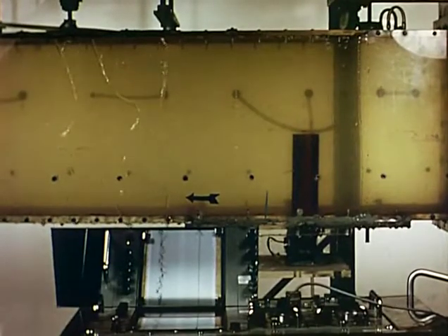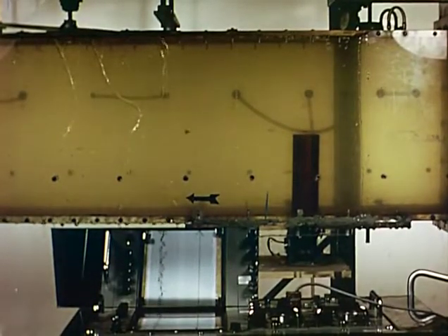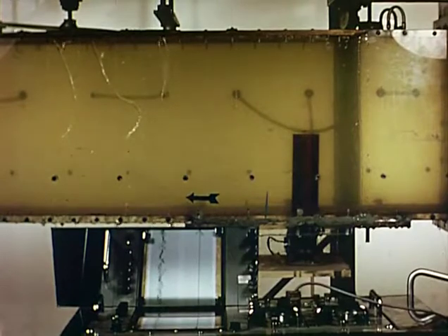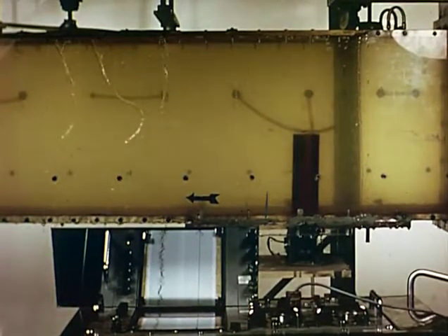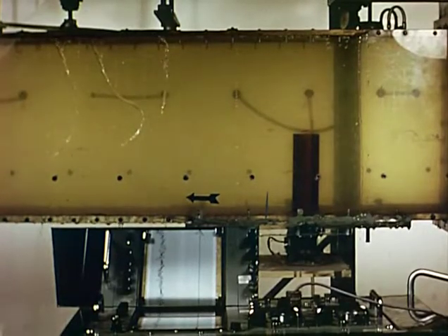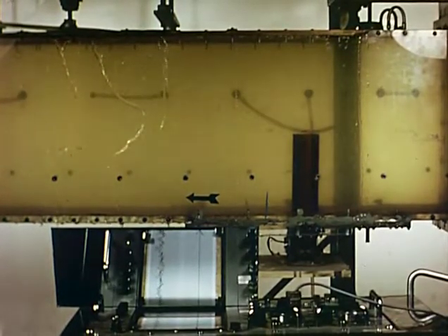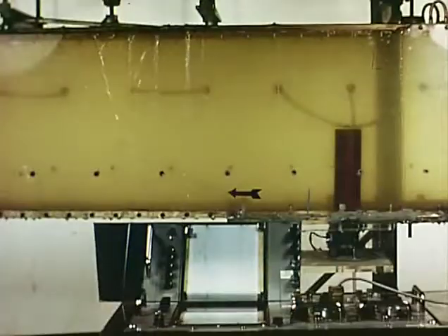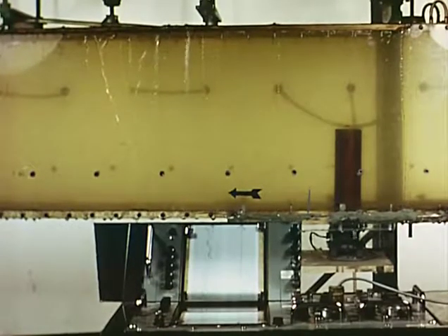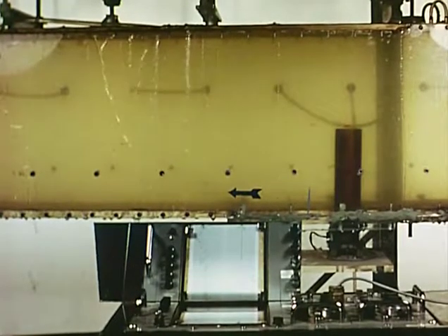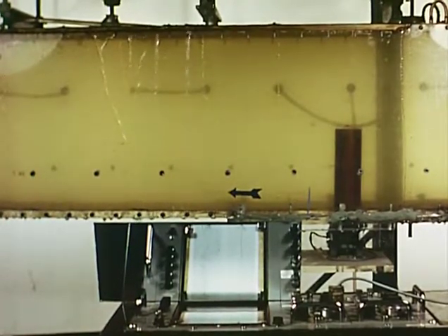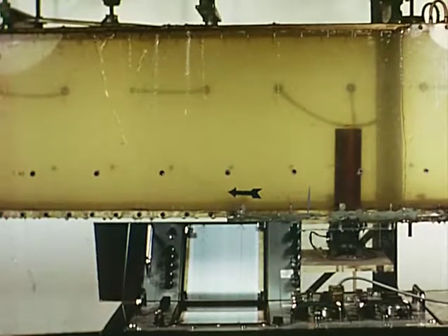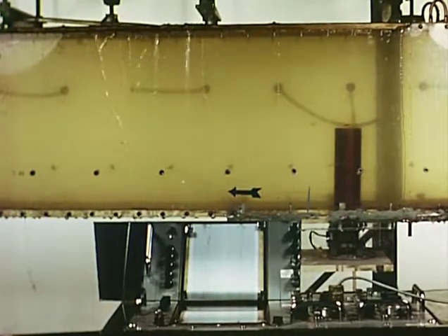Forces and vibrational frequencies were measured on the cylindrical injector. A sensitive strain gauge dynamometer was used in measuring the vibrational characteristics. The nozzle is supported entirely by the dynamometer. A Sanborn recorder is used to record the output of the dynamometer for later analysis. The tunnel velocity, which was initially 5 feet per second, has been increased to 7 1/2 feet per second.